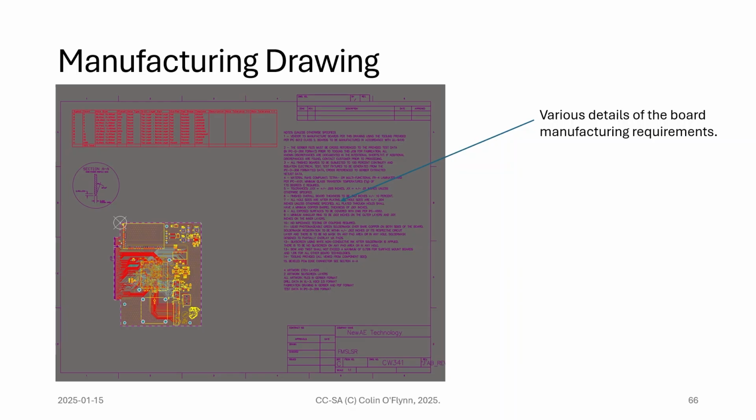So this is just another Gerber file. It has an outline of the board. In this case, Altium helps me include a photo of the board on it, or a render of all the layers, so you can see it here. But it has a whole bunch of notes.